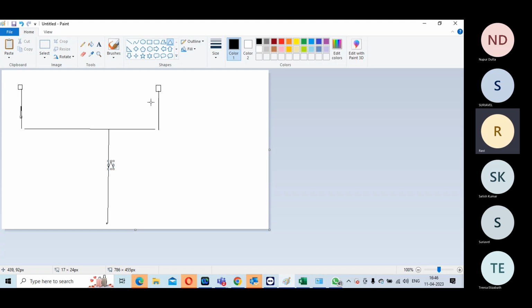That is information you have in the tool. You can say construct H tree, construct balanced tree. In CTS, you have that option of which tree to build. But not all options are there. Fishbone and others are manual. But you have HP cluster, fully balanced. You can set clock tree options and choose using that switch. Yes, you can choose. Clock tree has so many attributes, so many switches. You have to learn that.